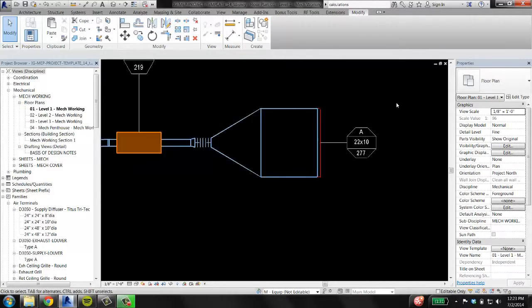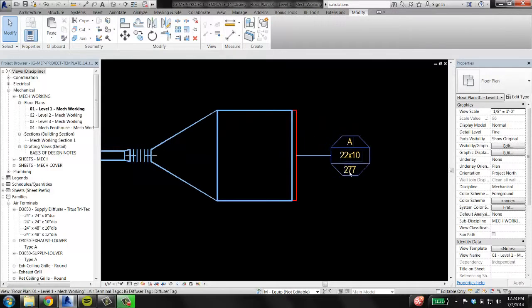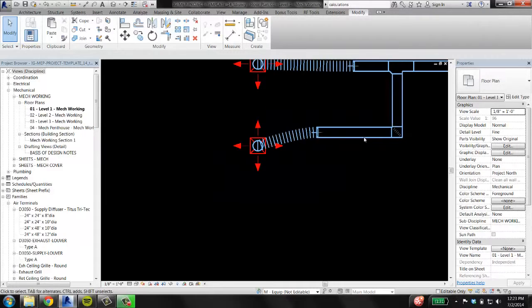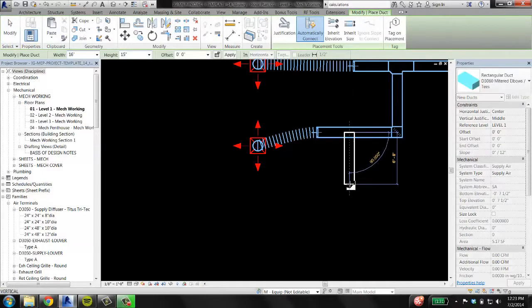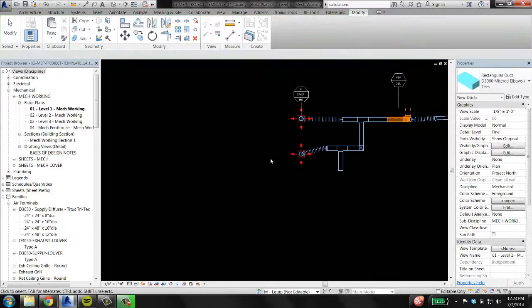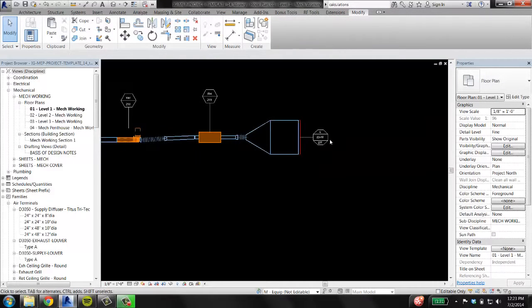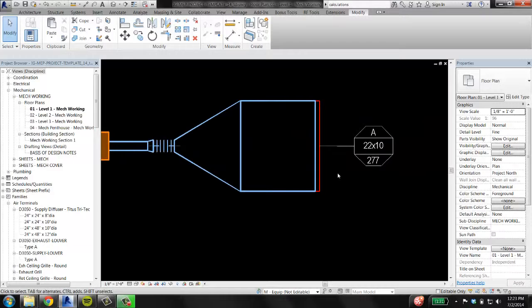You might not want this louver to be reporting this value because in a complicated duct system, if you have open connections and things that aren't quite right, this value might not be what you want it to be design-wise.